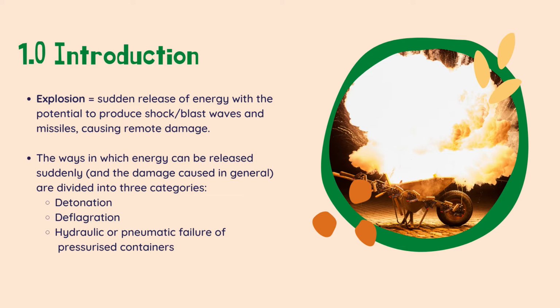Explosion is a phenomenon resulting from the sudden release of energy with the potential to produce shock or blast waves and missiles, where both of these can cause remote damage. The ways in which energy can be released suddenly and the type of damage caused in general can be broadly divided into three categories, which are detonation, deflagration, and hydraulic or pneumatic failure of pressurized containers.